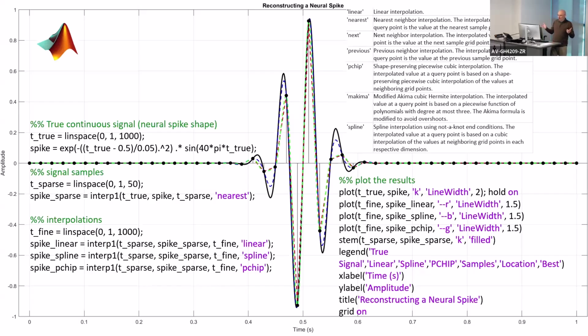Maybe you need zero-order hold if you're using a real-time embedded board and you're sampling your signal, and you want to convert it into a continuous signal instead of discrete points in real time. So how would you do that if you don't know the future? You just keep whatever was before, or you keep the previous linear extrapolation. These are the methods until you get the next point, and then you correct it.